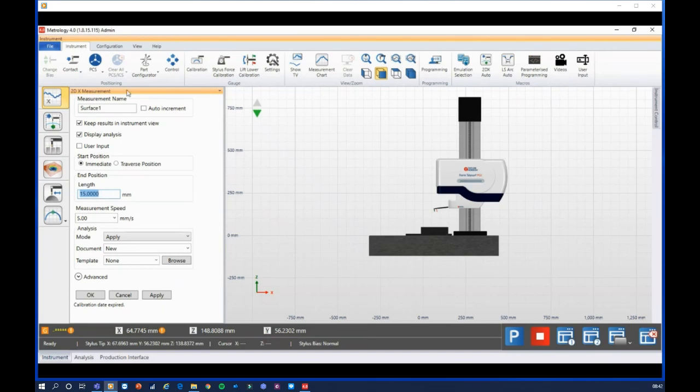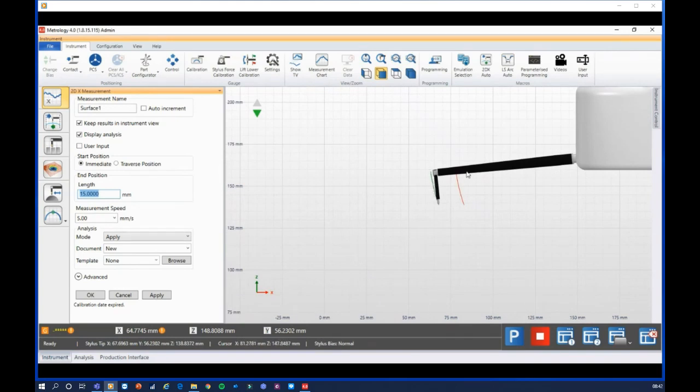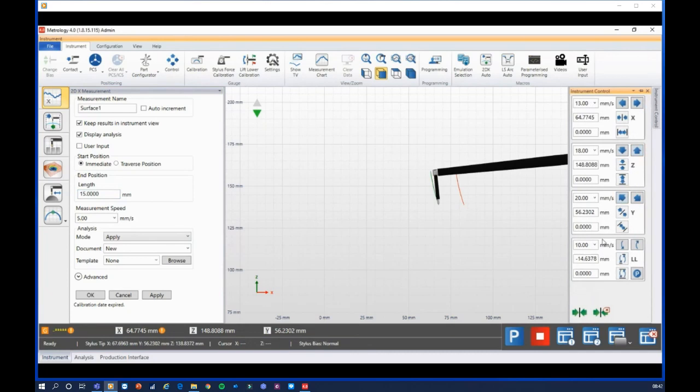but one of the things that I would like to show at this point, because I've opened this 2D window, is that we've got some additional things happening around the stylus tip. So using this zoom function at the top of the screen, I've zoomed into the stylus, and you can see these curved shapes. These represent the measurement range, and I'll just lift the lower so that the stylus is in the middle of its range. So you can see now the vertical range that I have, and it's obviously in a curve because of the arcuate motion of the stylus.